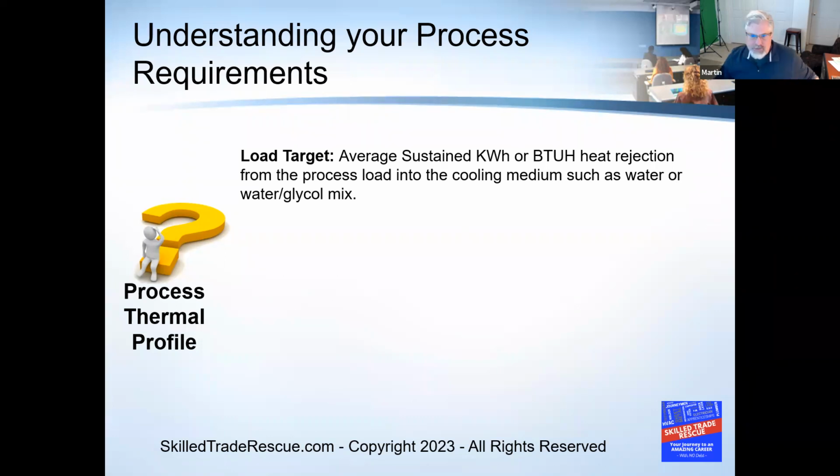What you need to do is ask whoever you're working with, whoever is requesting the quote, you want to get what you call the run sheets on those heat exchangers. And the run sheets are basically a document that says, under the design specifications, here is what the rejection is going to be from the hot side of this heat exchanger to the cold side into your application.